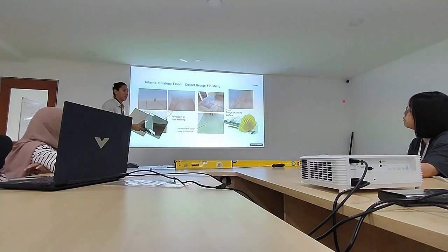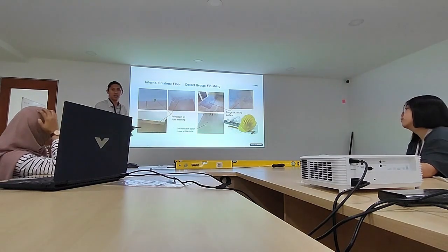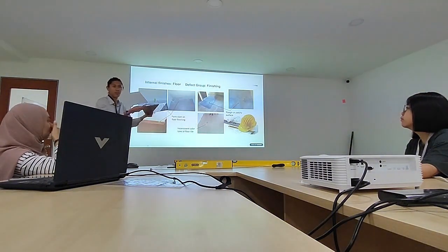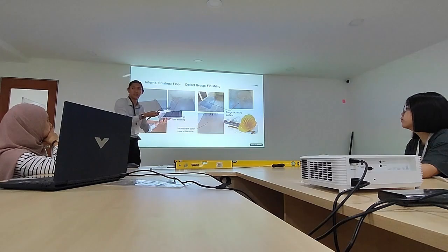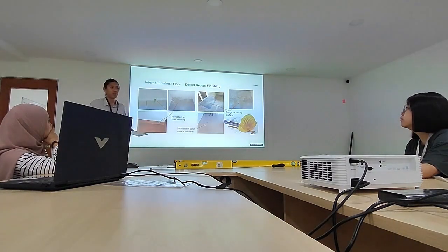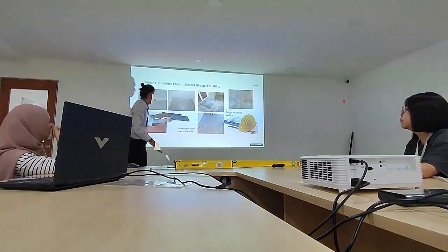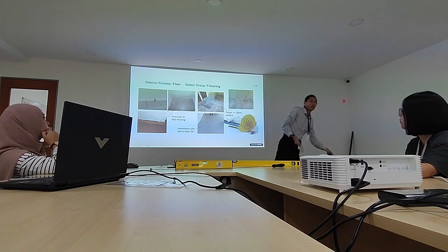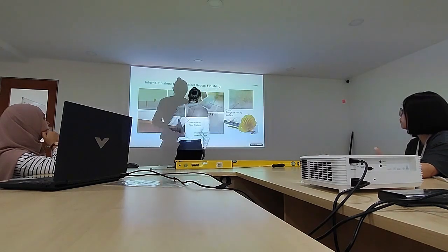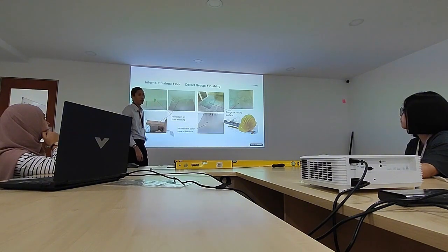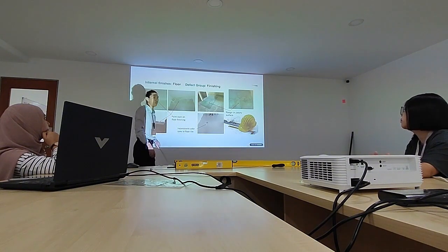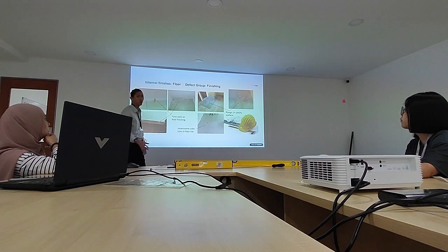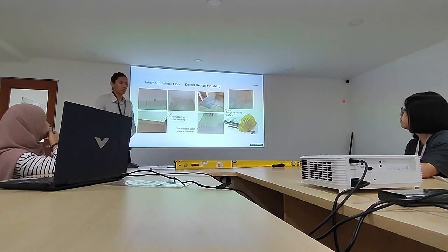Even though the tile code is the same, the batch may differ, so they can do the calculation. So what the site can do is put tiles with the same code on one side and use the same unit. When repairing, we use the same batch. This problem will happen when the site uses the wrong batch. This unit is batch A, batch 1. And when repairing, the whole corner is what we repair.